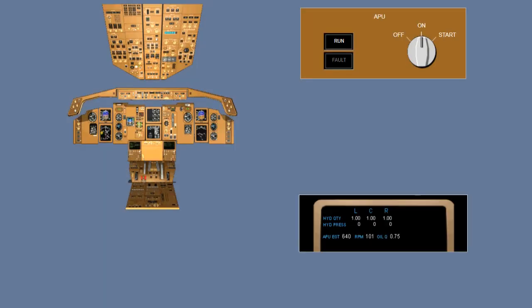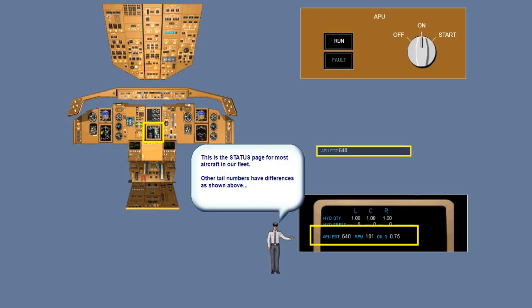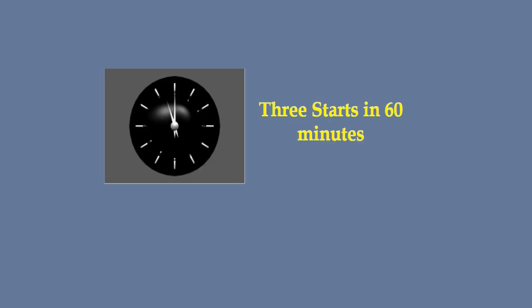The aircraft battery supplies power for fire protection, the APU fuel valve, and the DC fuel pump in the left main tank if there is no AC power on the airplane to activate the left main tank forward AC fuel pump. It also serves as a backup source for the control circuitry if the APU battery drops too low because of heavy starter motor load.